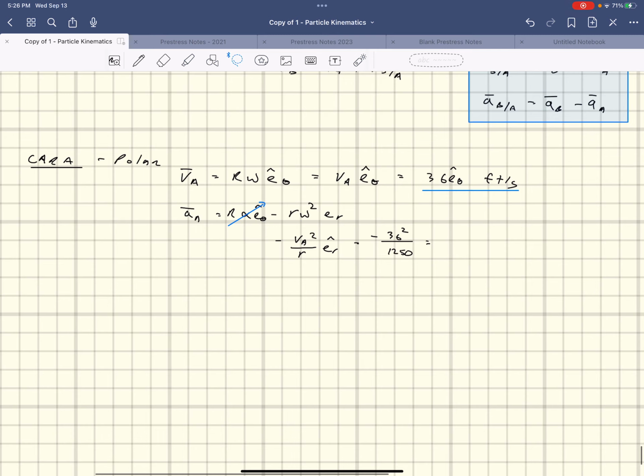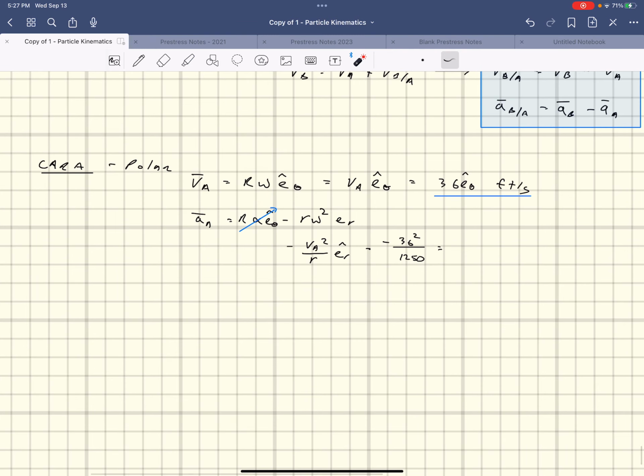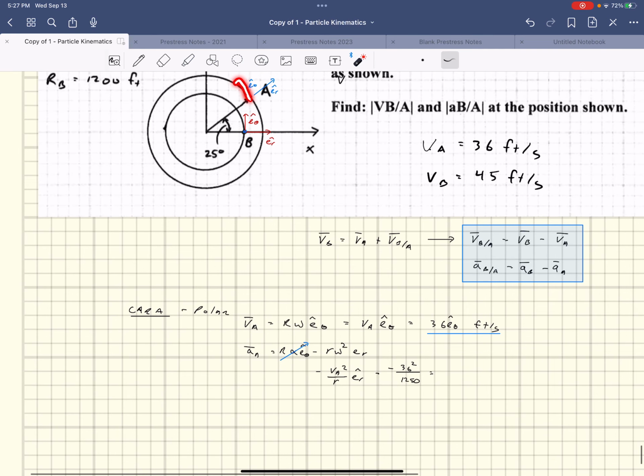Acceleration at A, right? This is the equation you would use for that. It's R alpha minus R omega squared. Again, this is tangential acceleration. This could also just be a_t, or in normal-tangent it was just the acceleration of that. Or in this case, just like R omega was the velocity, the acceleration of the vehicle in the e_theta direction would work. In this case, it says it's traveling at a constant speed. So if it's at a constant speed, that means there is no acceleration around that circle. There is no acceleration in this direction for either one of these things.